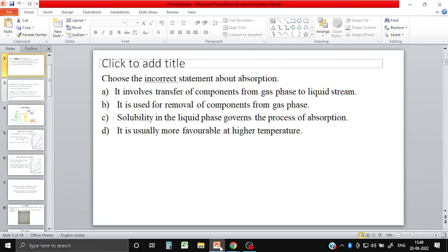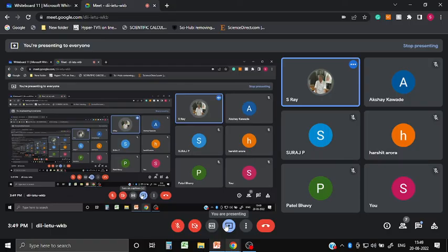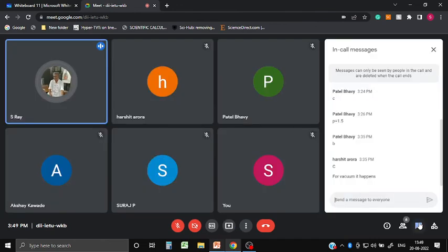So if you change the submergence by controlling the opening of your hot bypass line, which is nothing but the pressure drop across the condenser, the amount of submergence of the tubes in this condenser would change, and this would change the liquid temperature inside the condenser and its corresponding bubble point.